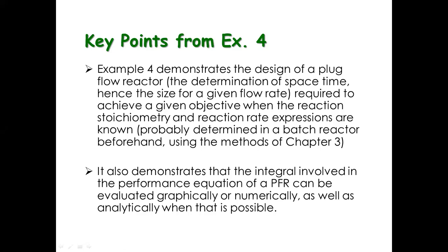So in this case, we are already given the rate law because the problem gave it already for us. If not, we'll be the one to determine it using the integral analysis or whichever analysis is applicable. Now, this sample problem also demonstrates that the integral involved in the performance equation for a tubular reactor can be evaluated graphically or numerically. Now, this was exactly copied from the conclusion of Levenspiel when he discussed this sample problem.